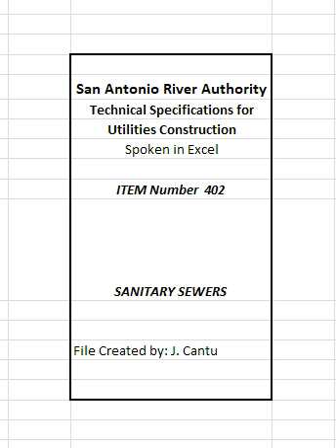2. Water line/manhole separation. Unless sanitary sewer manholes and the connecting sewer can be made watertight and tested for no leakage, they must be installed so as to provide a minimum of 9 feet of horizontal clearance from an existing or proposed water line. Where the 9-foot separation distance cannot be achieved, a carrier pipe as described in 1D, above, may be used where appropriate.